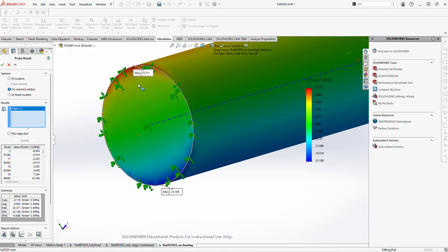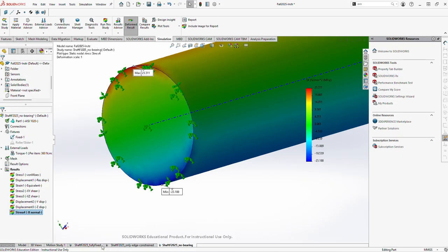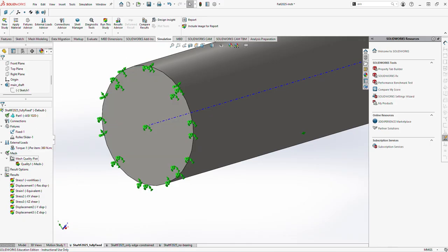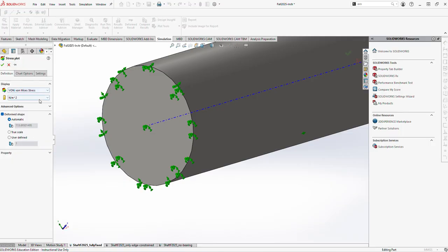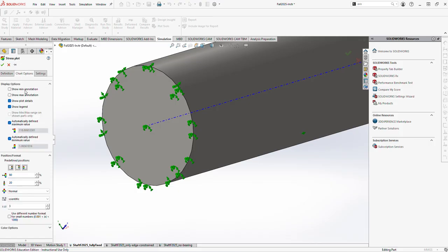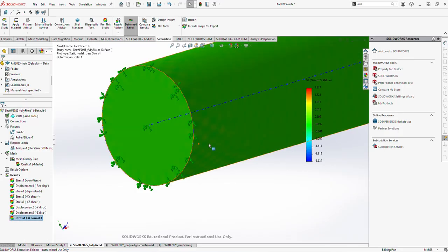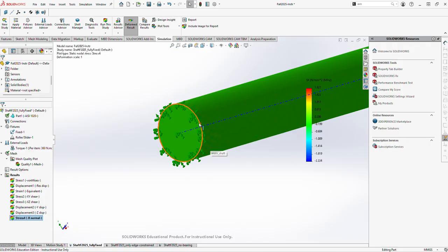You can compare this very quickly with the correct model that was over here, right? And here, if I now plot x-axis stresses in megapascals, true scale, showing both maximum and minimum, floating. Now you can see here that the maximum stresses at this constrained edge are also very, very small. Can you see that? Yeah, it's only 1.827 as compared to 23 megapascal.